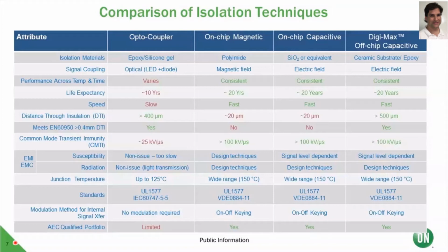With the on-chip solutions and the 20 micrometers, it guarantees only about 70 volts of intrinsic working voltage. Any voltage above that, up to the maximum working voltage rating of the part, which is typically several hundred volts to over 1,000 volts, has to be guaranteed by the integrity of the insulating material between those conductive points inside the package.